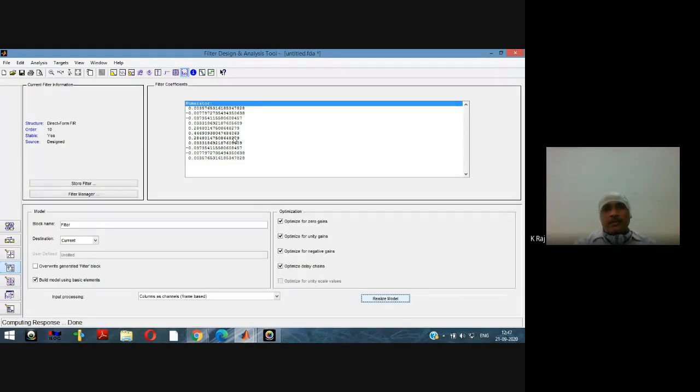And after getting these 6 pieces of information, now we will move towards the designing of the filter. That is, we will select the response type: low pass, high pass, band reject, or differentiator. And after this selection, we will select the design method, FIR or IIR. And once we have selected a particular design method, there are different types